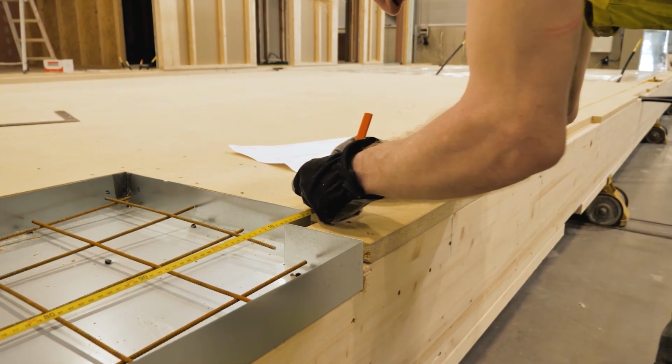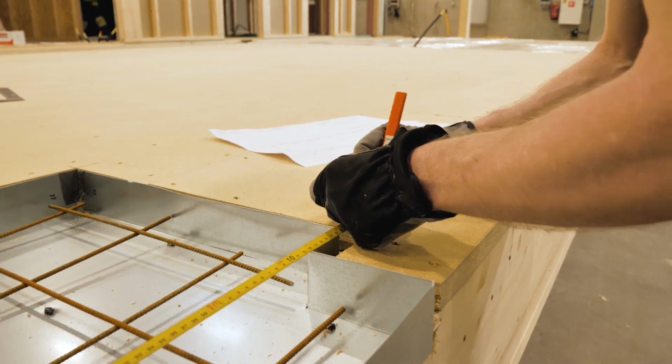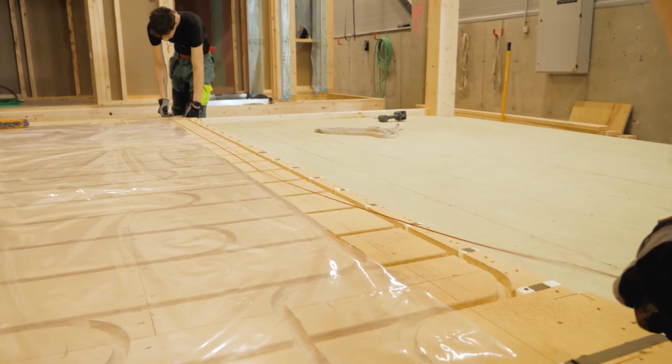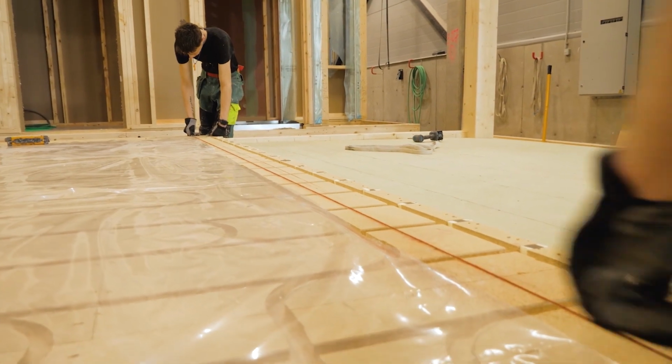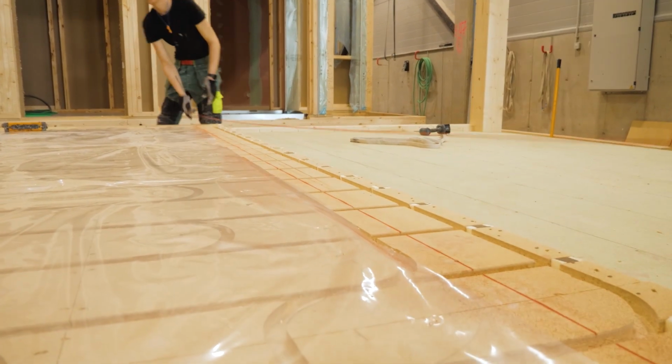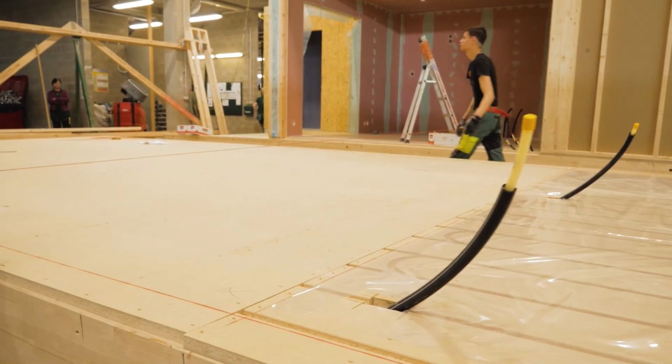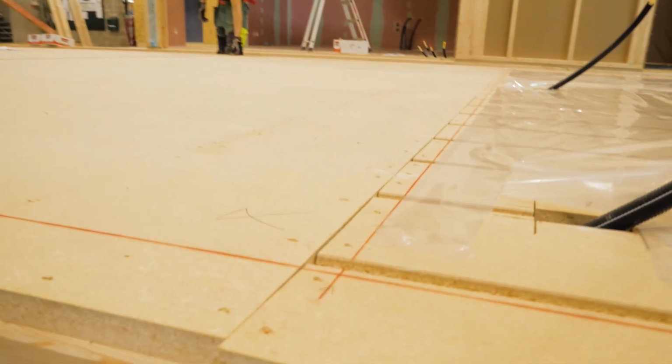On the floor element, the locations where the wall panels must be installed are marked according to the working drawing. If necessary, the end points of the markings must be shifted to achieve the right angles of the outer walls. It is important to make sure that the outer walls are located at right angles.